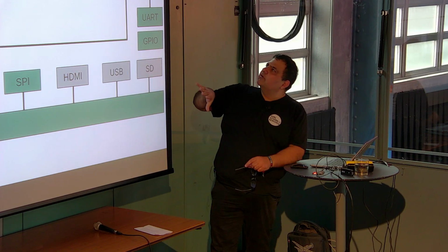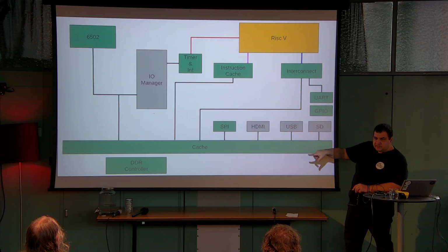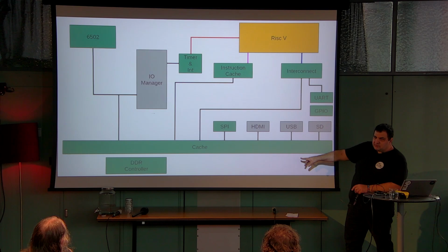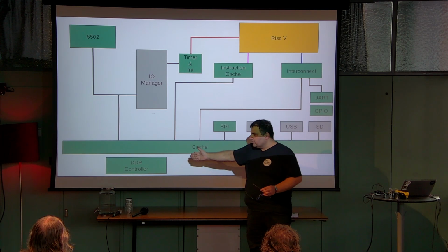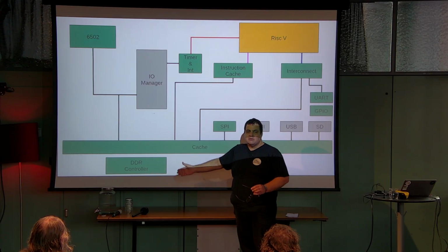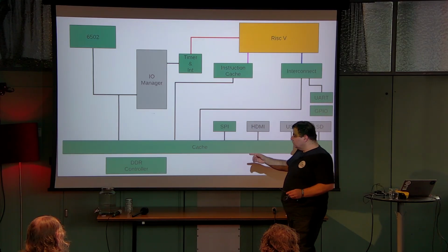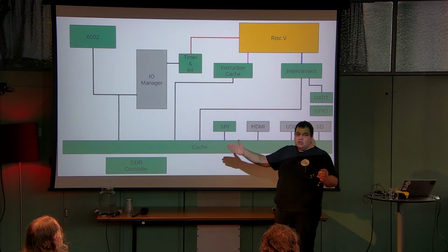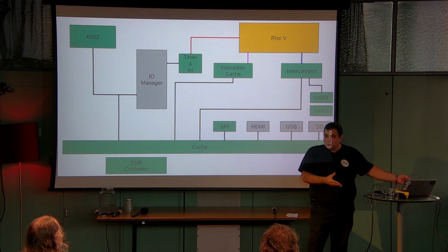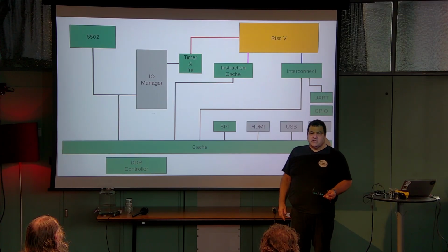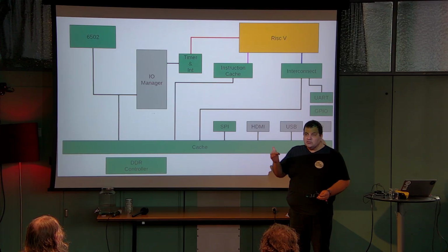Now, what you're seeing here, the gray areas are not yet written. And the green areas are ones that I wrote myself from scratch. Now, you might wonder, why on earth would I write the DDR controller from scratch? That does not sound like fun. It isn't. And the reason is, well, yes, Vivado has a ready-built DDR controller, which you can just synthesize and add to your design. It's 4,000 LUTs. Remember, I have 8,000 LUTs total.